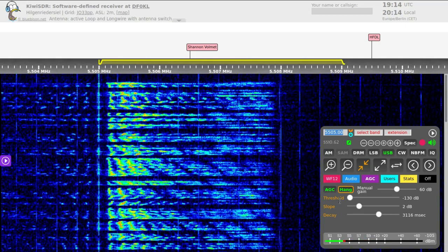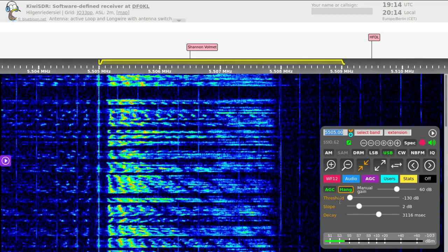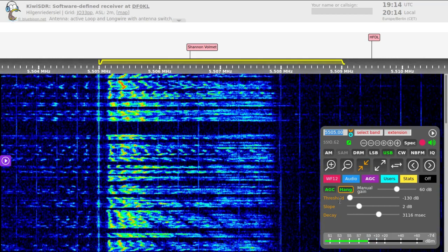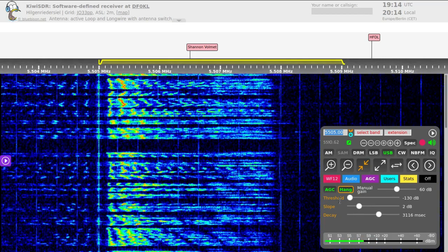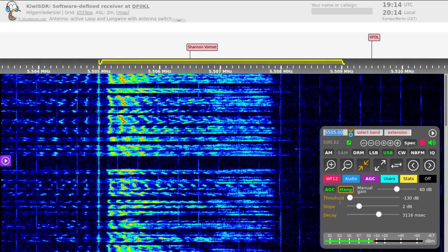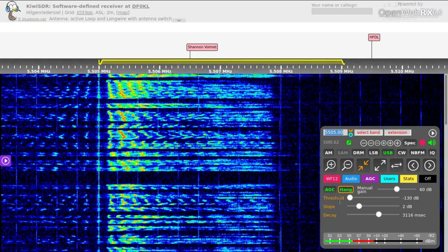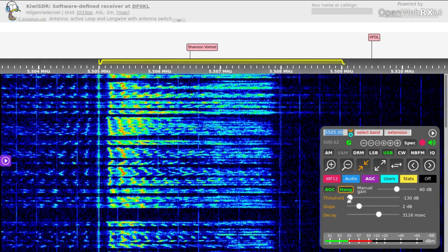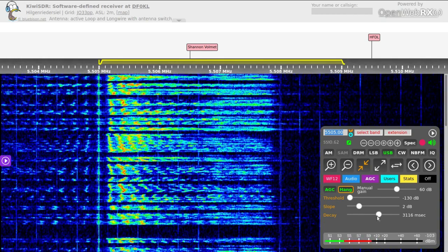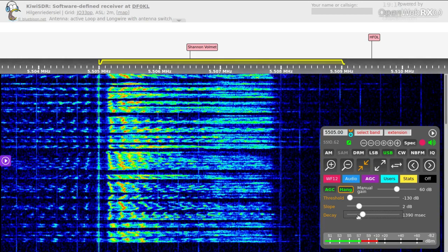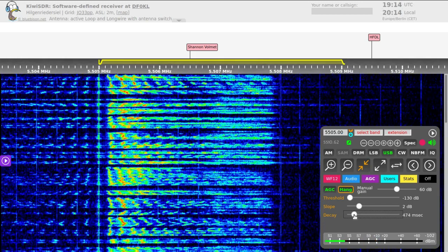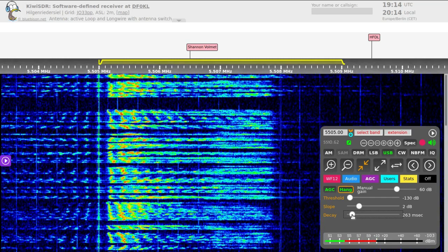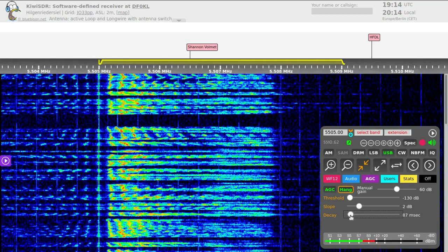Bringing the threshold all the way back up to minus 130. You'll notice that the decay time will keep the gain reduced in between syllables. If the signal fades, though, you will be subject to quite a bit of noise. Now, for a few moments, let's reduce that decay time again to make a point about the rapidity of the automatic gain control and the effect on background noise.